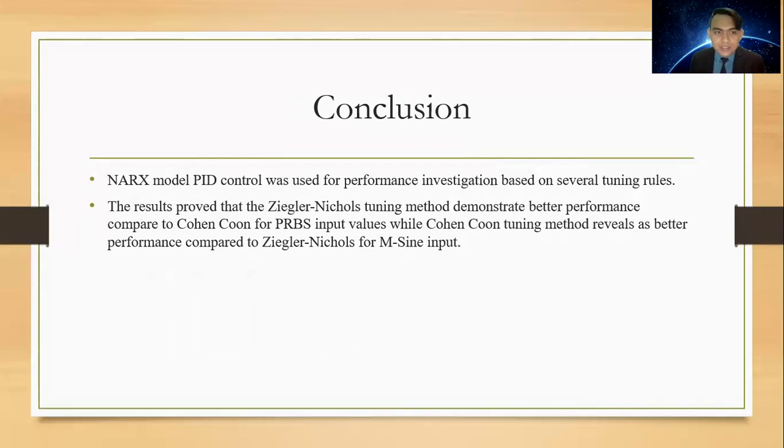In conclusion, the NARX model PID control was used for performance investigation based on several tuning rules. The results proved that the Ziegler-Nichols tuning method demonstrated better performance compared to Cohen-Coon for PRBS input, while the Cohen-Coon tuning method revealed better performance compared to Ziegler-Nichols for multisine inputs.